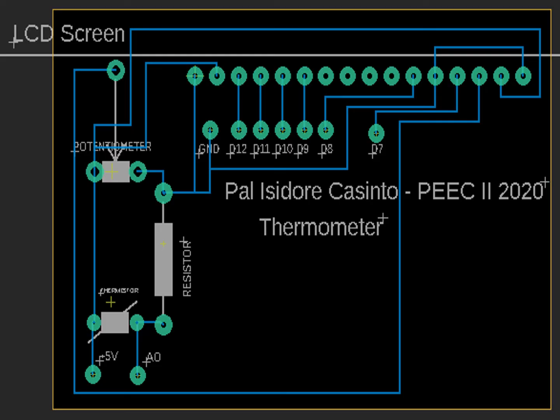Moving on from the code slide real quick, we're just going to go over the PCB design layout. What you're seeing in blue here are just the laser tracings, the metal connections that will be made to each component. And in green, these are just the pads, and we custom edited the pad diameters as well as the hole diameters so that there's enough surface area for soldering as well as the proper fitment for each of the different components.